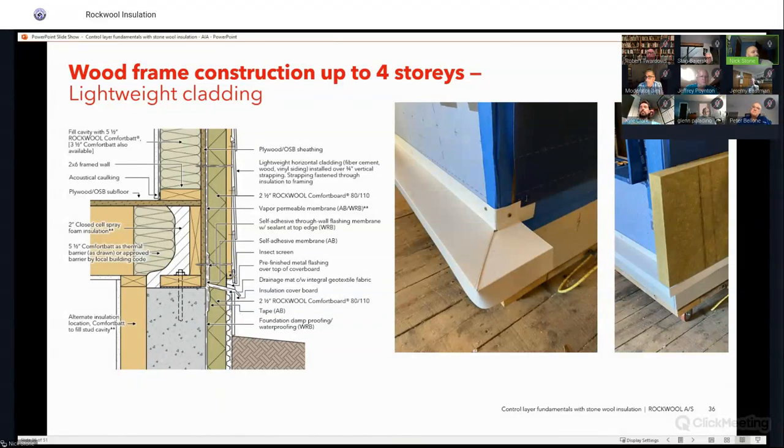When it comes to strapping on these rain screens, I'm a big believer in 3/4 inch strapping as the best thickness. I've done a lot of different thicknesses to check on for ventilation, and those work fine. But when it comes to putting on your siding and trim, 3/4 inch is really the minimum that you want to go with. When you go thinner than that, you tend to get some waving when you go to put that siding or trim on. So 3/4 inch is something I highly recommend from a strapping standpoint.